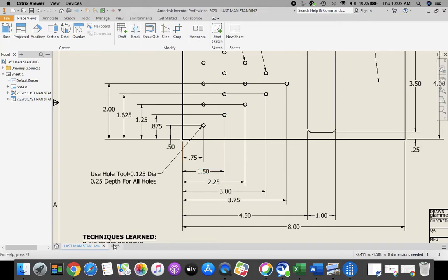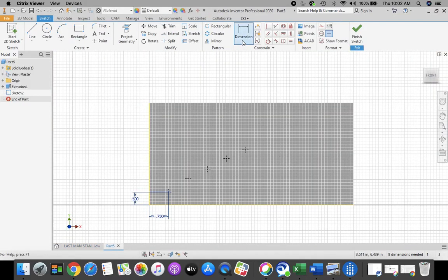side. Going back to our drawing with our dimension tool, I want to click the bottom of my part, go up to that second point, bring this dimension out to the side. You see how this was already highlighted in blue, so I don't have to press delete. I can just type in 0.875 and it replaces the value that's in there. Green check mark or enter on your keyboard.